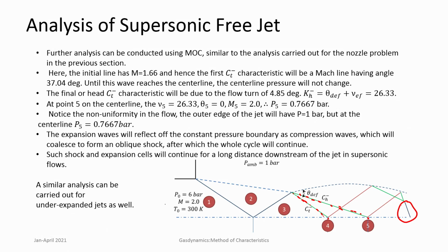So we saw now that the method of characteristics is a very useful technique, not only to look at the design of contoured supersonic nozzles, but to solve supersonic flows in general. If you can find regions where the flow is isentropic and also non-uniform in general, that can still be solved using the method of characteristics, provided you know some initial conditions and you can march from that initial condition into the flow field and solve the entire flow field.